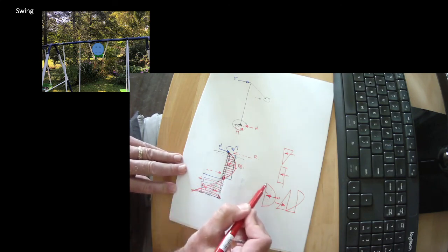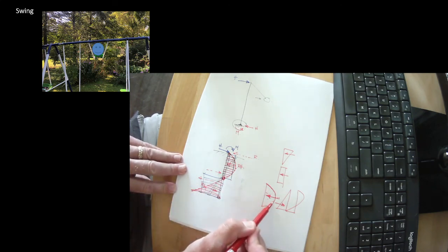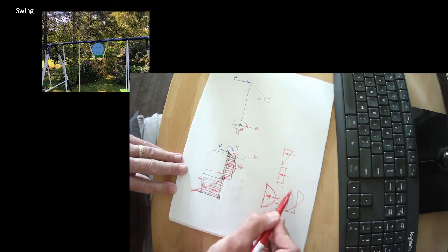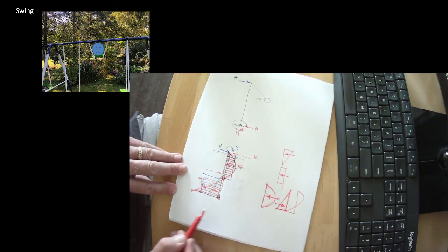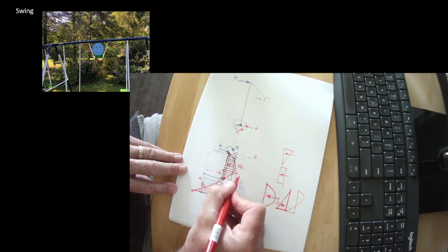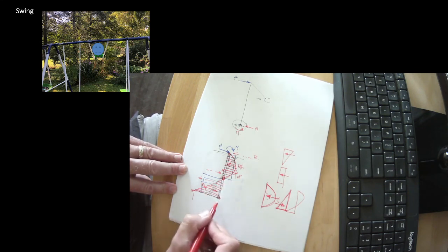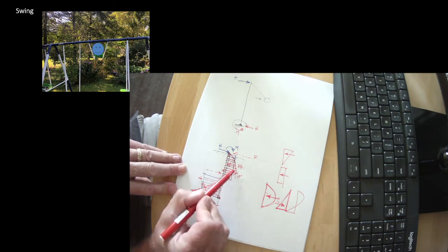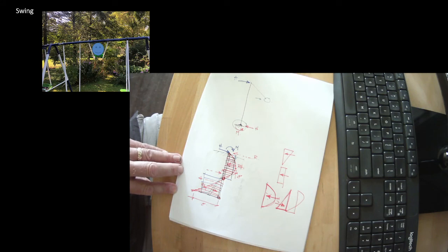Once we've done that, once we know the reaction, we know the magnitude of our parabola, we know the magnitude of our triangle, once we know the resultants, from that we can determine the peak stress and the peak stress, and we can check to see if these two peak stress points exceed the capacity of the soil.